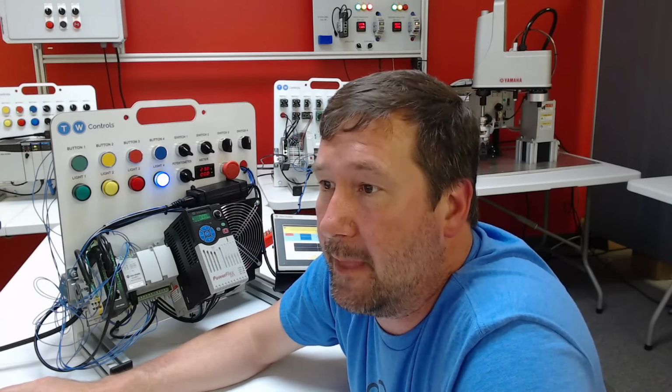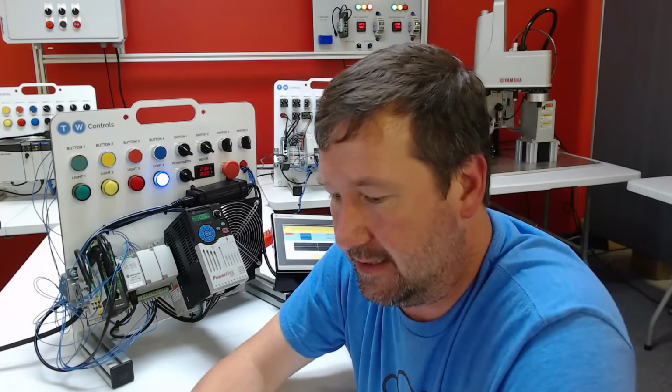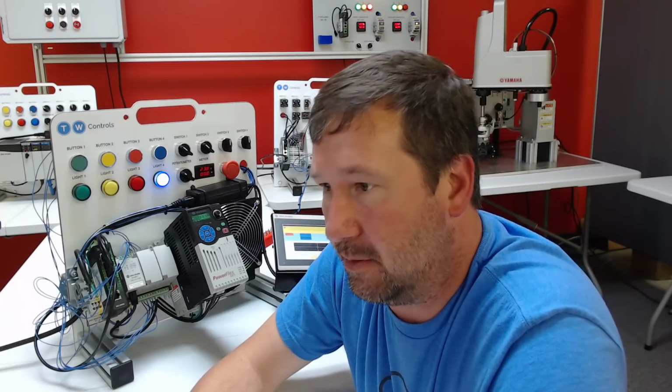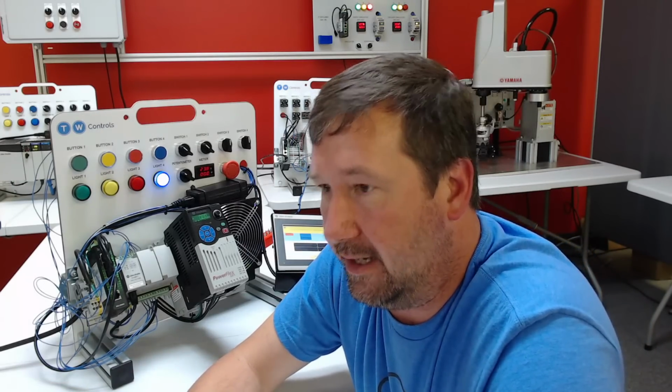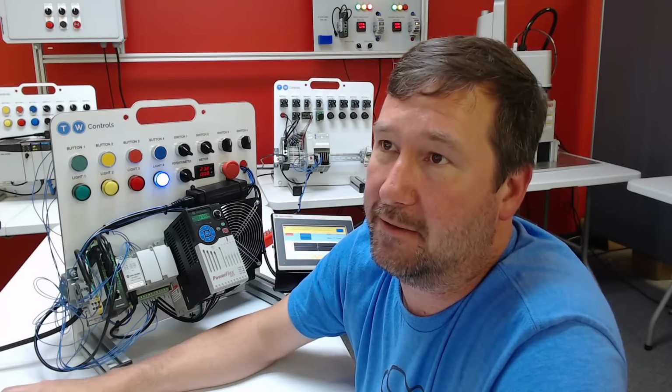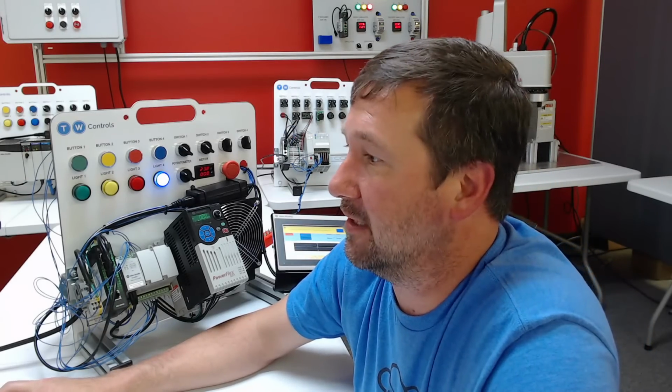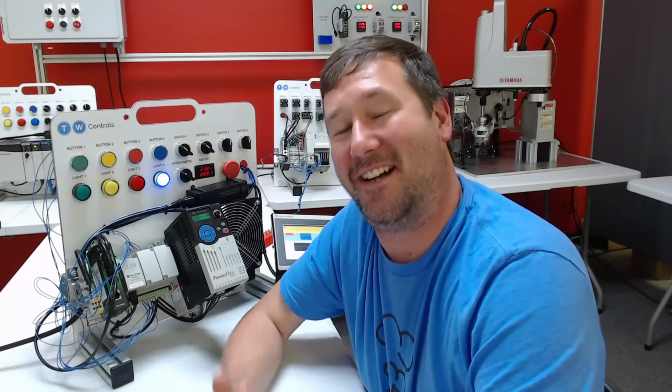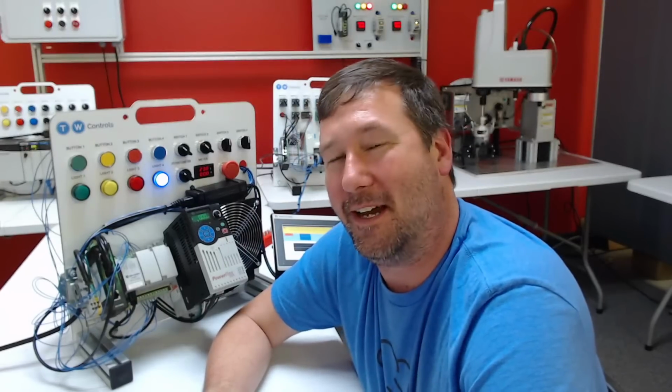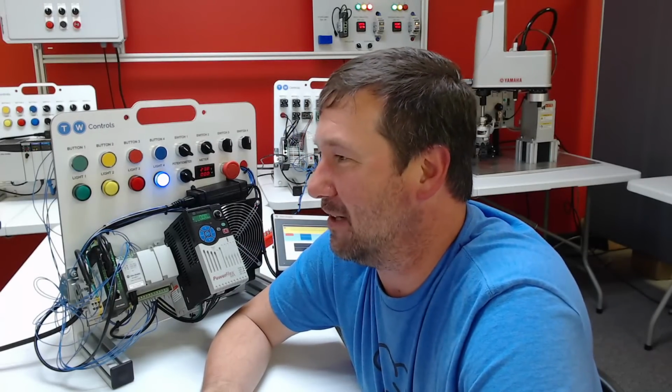So we'll go offline. And yeah, right here need to say T number 1S. And now we can download that and that should fix it. Thank you, John. Yeah, you're right. No timer value.